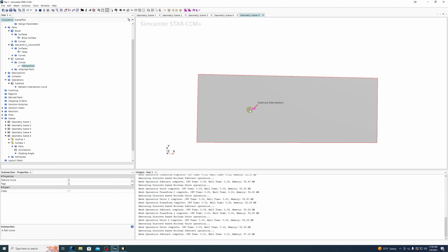You create the thing, whether it be an airfoil, a wing, a plane, a boat, what have you. You model the actual thing you're interested in, and then you create an enclosure for fluid around it. And then you cut away the body of interest, again, boat, plane, airfoil, whatever, away from that fluid. So you have your fluid, and then you have a hole in the middle of the fluid that's shaped like the thing you're interested in. That's kind of a general way to approach modeling something to prepare it for CFD.